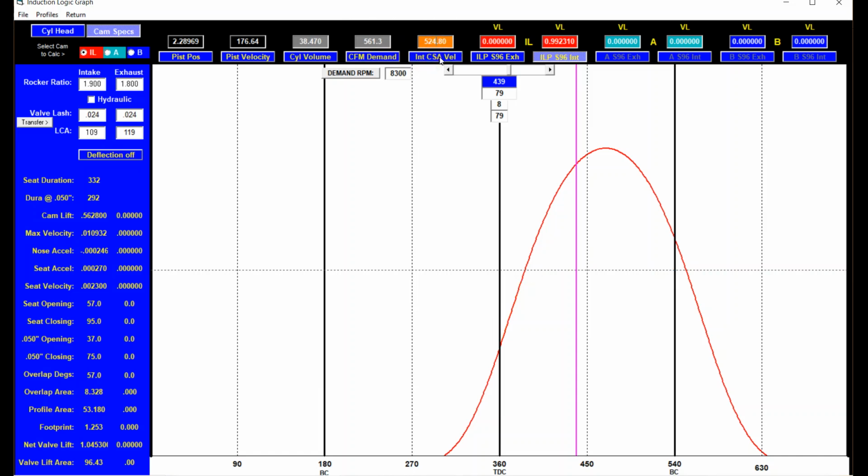Now we can turn that off and look at the velocity of the port. 706 for the intake average cross-sectional area. 748 for the minimum cross-sectional area, and 736 for the throat velocity. Yeah, you drag racers will continue putting more and more gear in the car till the engine finally lays down. At that point, past peak horsepower, you'll have port velocity numbers that you'll know not to exceed.